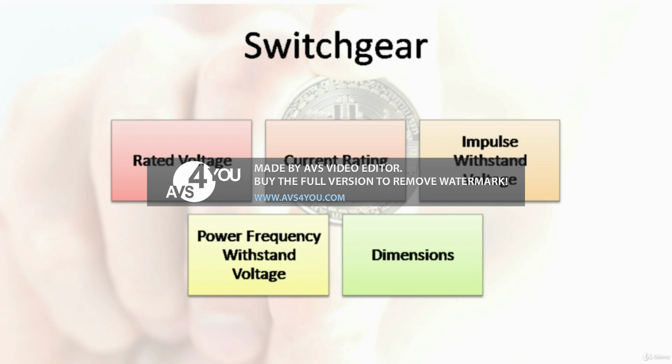Medium voltage switchgear can be relatively complicated to spec, as it has a plethora of components such as meters, circuit breakers, contactors, fuses, surge arresters, PTs, CTs, and various relays, etc. You don't need to know all of the intricacies of these components, as usually the manufacturers, and I'm talking about the big ones, will already pick the best ones, and they can tell you whether or not it meets the standards of your local region. What you need, however, is to look at the following properties to see if it suits your needs.